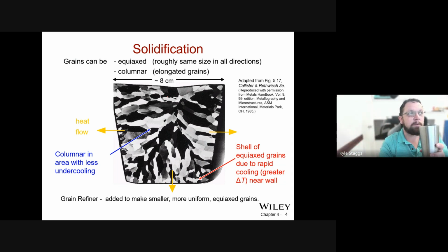That should make sense as the heat flows out on all sides of the mold. And the top will tend to have a sort of depression. That's a little exaggerated, but it gives you a sense of what is going on there. In order to get to your exact level, you might have to put in a lot more metal, especially because of how much metal is going to be consumed by creating the sprue.